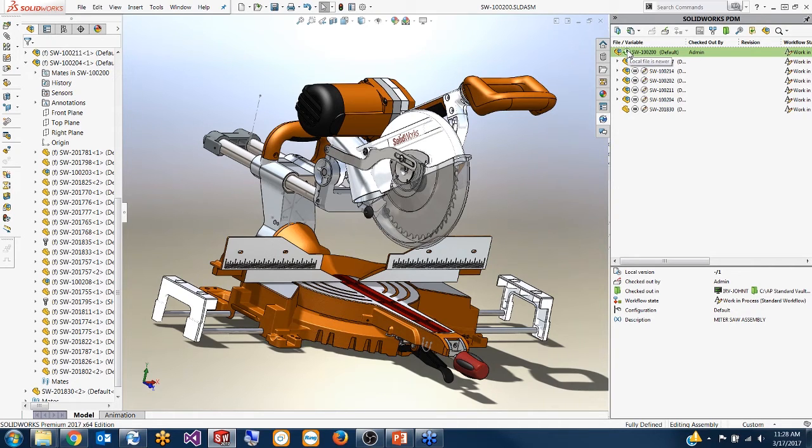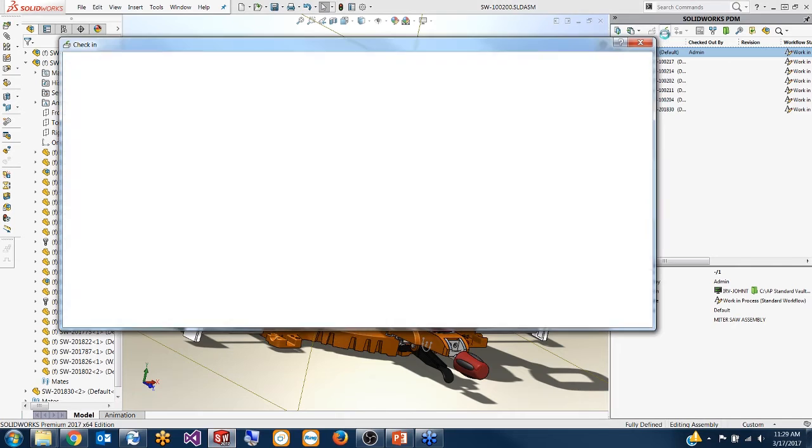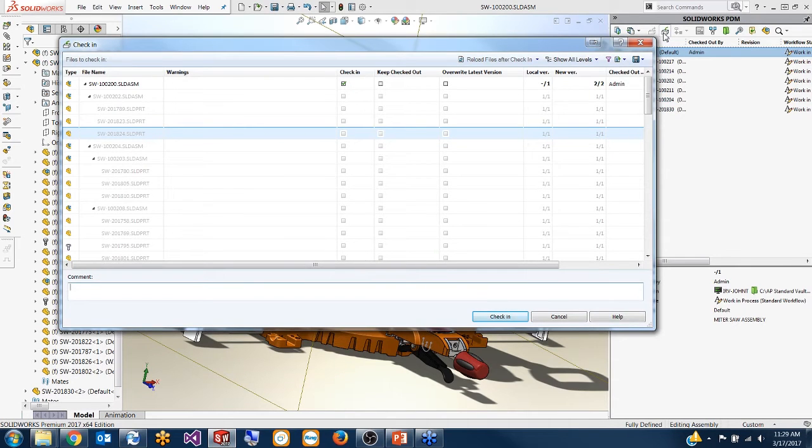Now, because my file is local, if you take a look on the right side of my screen here, there's that little special add-on. That add-on for PDM lets me know visually that the file I had locally is now newer because I did a Control S save, and it's more updated than the one that's in the vault. So the system inherently knows that comparison. Because of that, I know that I have to push this update to the server. All I have to do from an engineering standpoint is just push that change back in. So here's the second step that's new for your workflow.